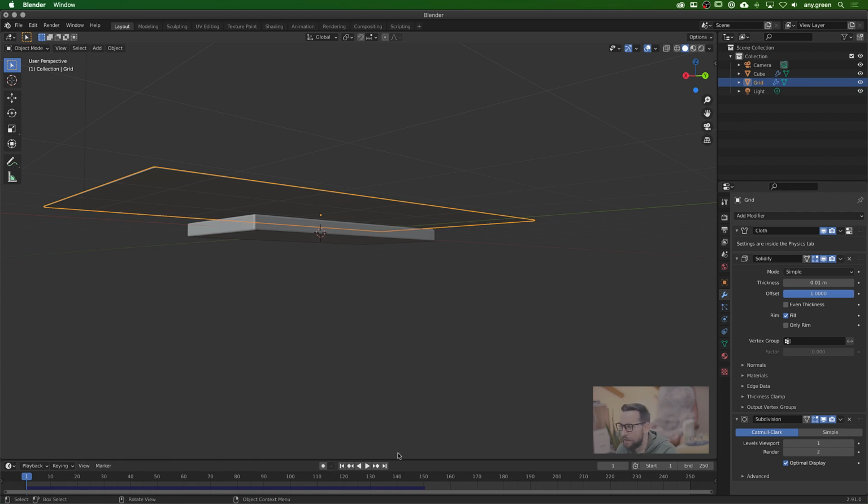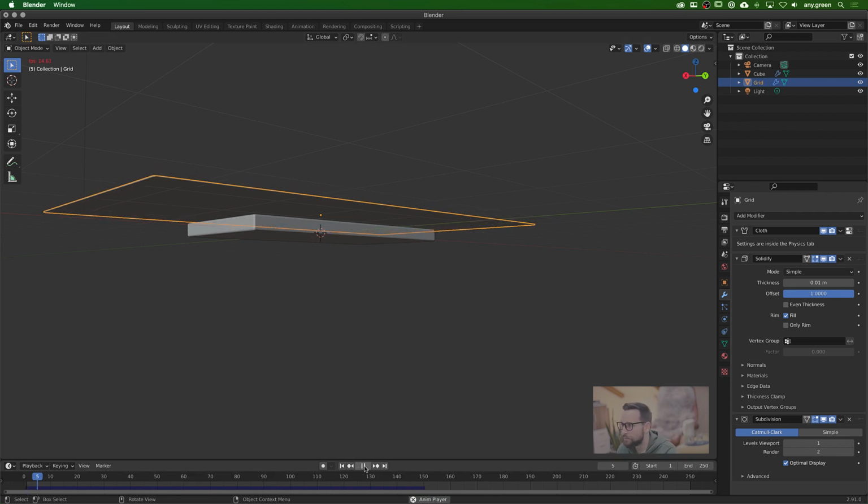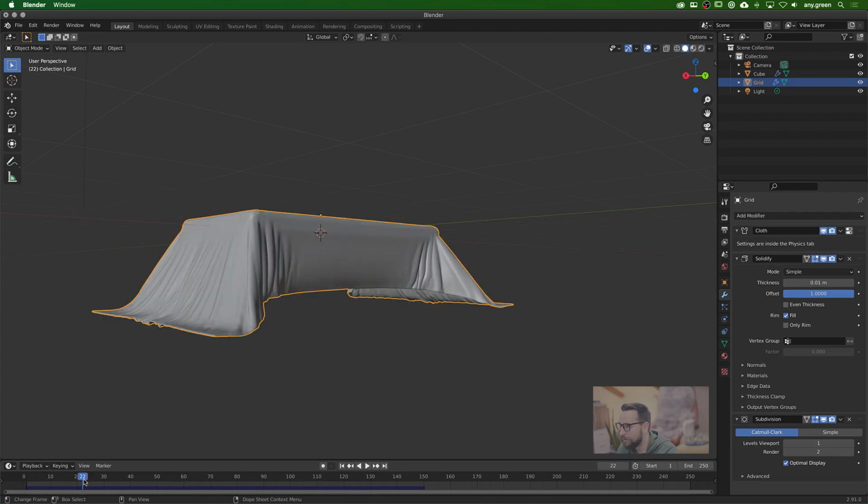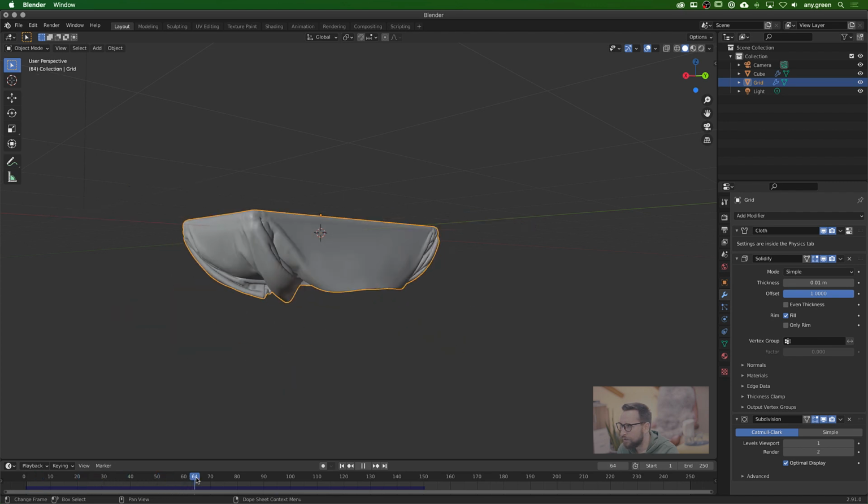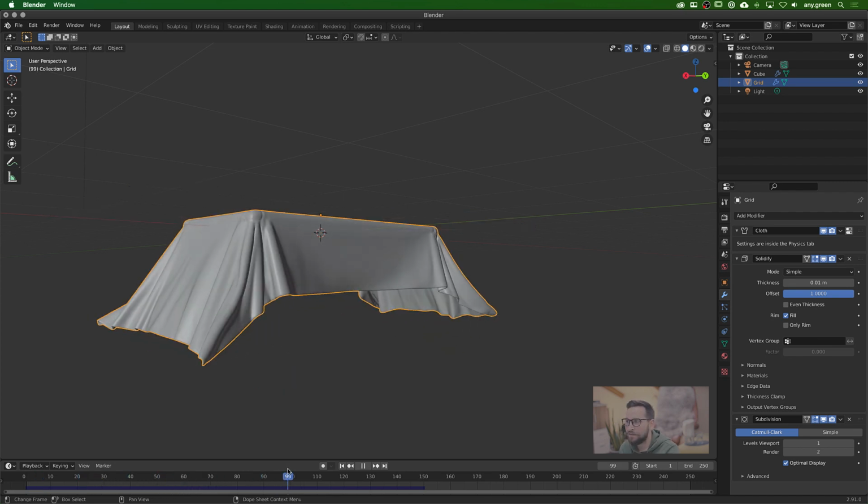One of the issues that we might have with the overlap that we have here, with the weird corner, could be because polygons are overlapping too perfectly. So if we just slightly offset our mesh, we might get a better result. And of course, when our resolution is higher, we might also get a better result, both for the resolution of our collider, so the table, as well as the resolution of our cloth.